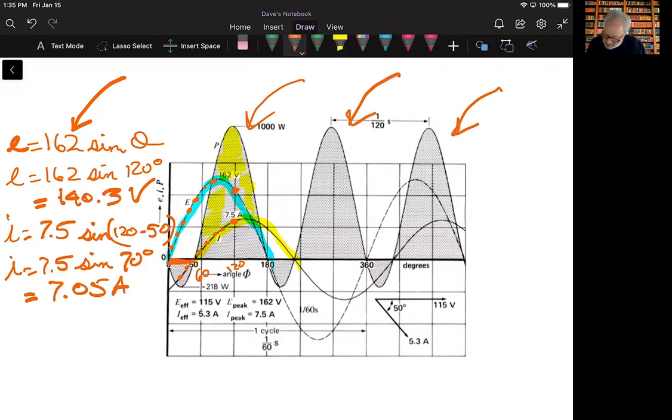And what I'm also going to see is if I go to this part here, and I take this voltage through one complete 360 degrees, and I also do that with the current, through one complete 360 degree cycle, then what I'm going to show is, and it's probably easier to see this with the voltage, that for one complete cycle of voltage here, 360 degrees, I see 2 cycles of power.